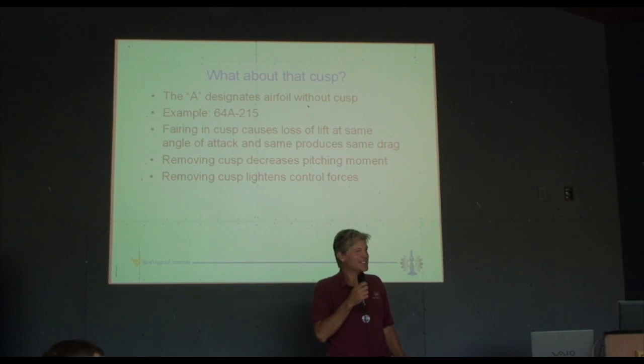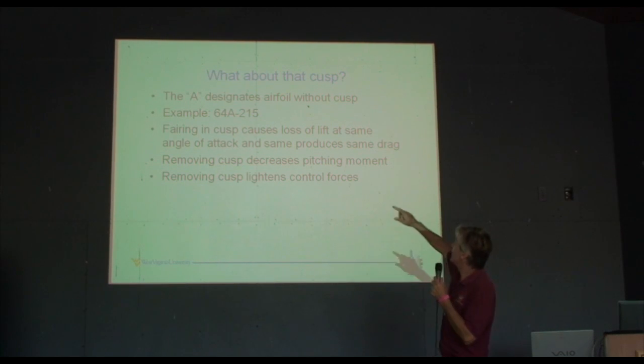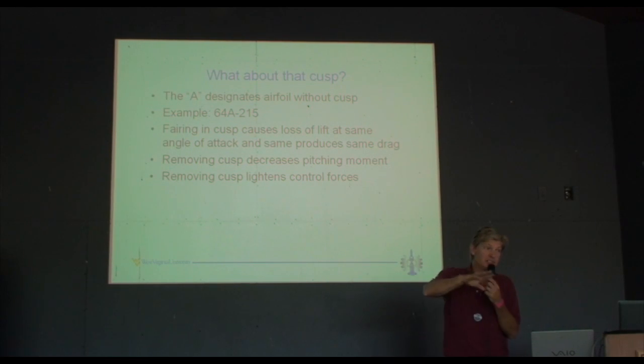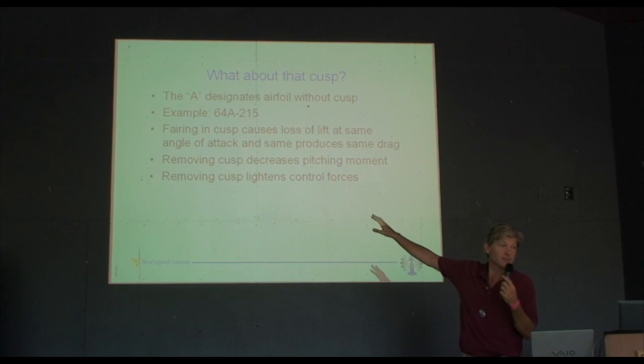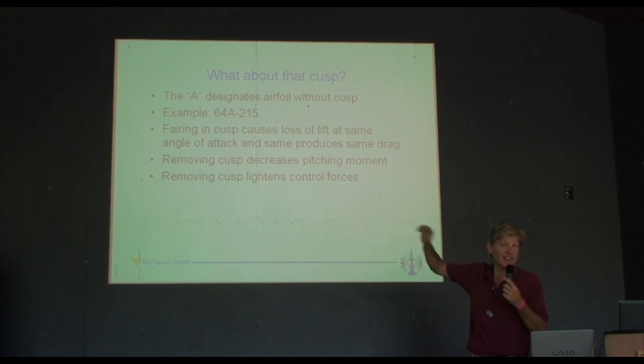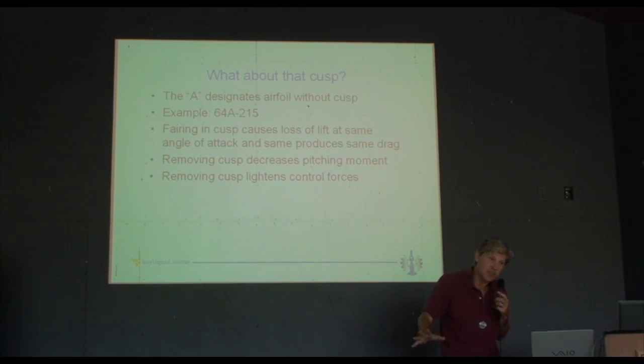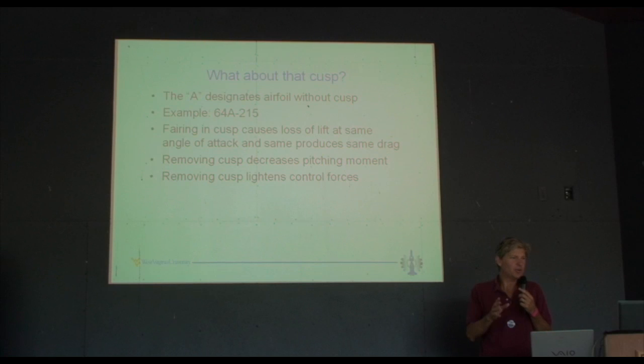Yeah, something like that. And so we have the A series that doesn't have the cusp. And you probably know this better than I do, you get some loss of performance when you take that little cusp out, believe it or not. But it's okay. And what else is there? You get a little change in pitch. It lightens up the pitching moment. The pitching moment goes down.